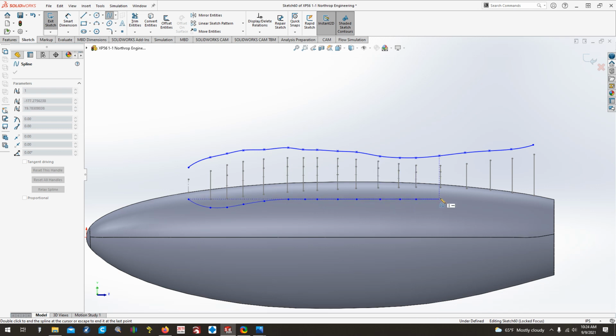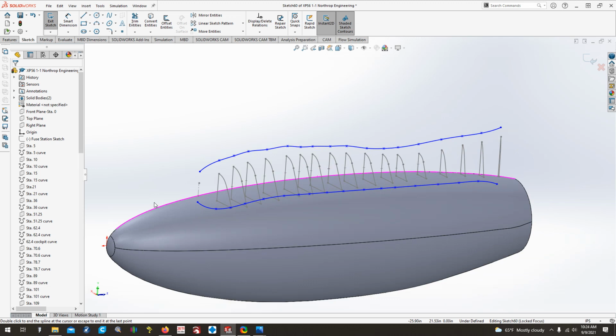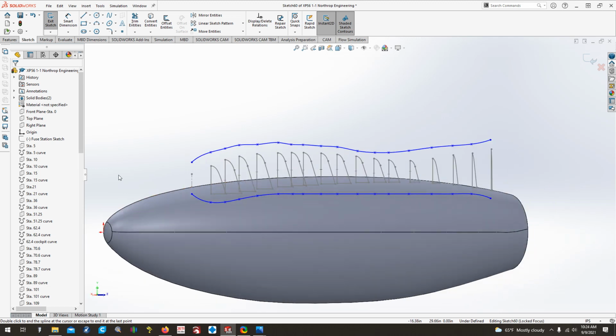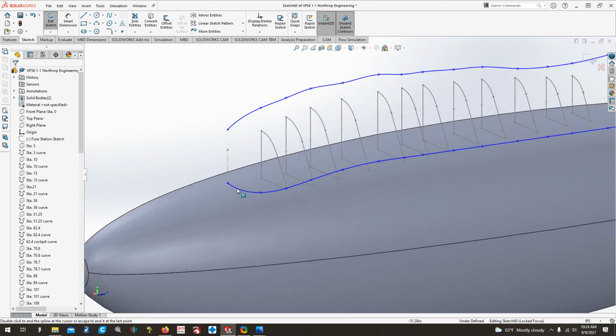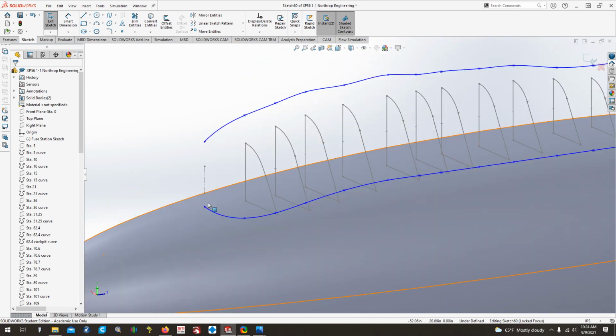And you'll notice all these little dashed lines that keep popping up. That just means the point that we're putting in is directly under the point from the spline above it. To the end, hit escape to exit. Next thing we'll do, again, use your little arrow keys here. I'm right key twice, down key once. That kind of twists and skews it for you.